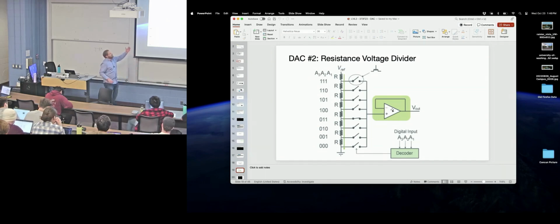Yeah, so in this case, you're probably going to set the op amp's positive rail to VREF, and the negative rail is going to be ground. And op amps in general, some of them can be specially designed to go rail to rail. They can output a signal. Sometimes they have to have a voltage drop, so you might have to have your op amp be higher voltage and lower voltage than the actual signal you want out.